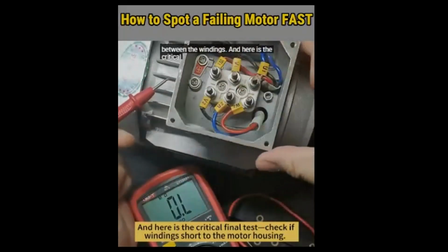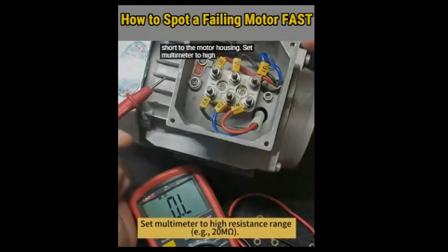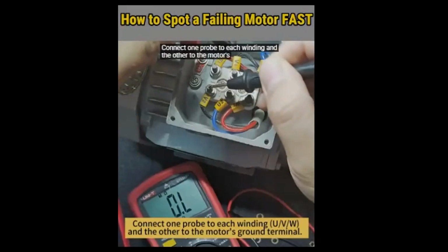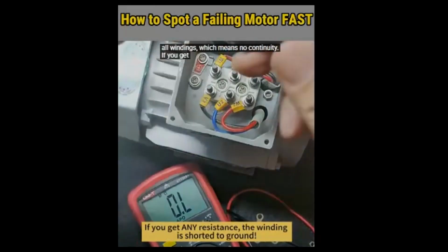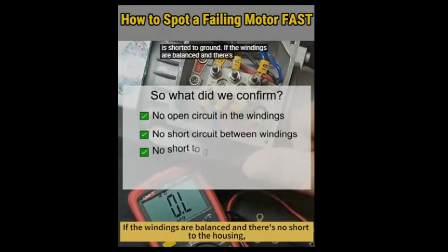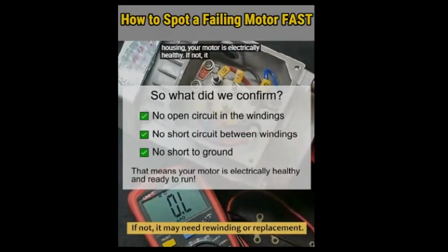And here's the critical final test. Check if windings short to the motor housing. Set multimeter to high resistance range. Connect one probe to each winding and the other to the motor's ground terminal. A healthy motor shows OL for all windings, which means no continuity. If you get any resistance, the winding is shorted to ground. If the windings are balanced and there's no short to the housing, your motor is electrically healthy. If not, it may need rewinding or replacement.